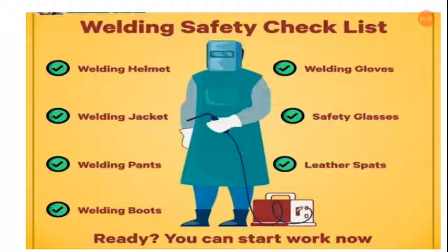Now you have to keep your clothes free of grease and oil. These substances may ignite and burn uncontrollably in the presence of oxygen. Avoid rolling up sleeves and pant cuffs because sparks or hot metal could get stuck in the folds. Wear trousers that overlap work boots, not tucked in, to keep particles from falling into the boots. Leather high-top boots with steel toes are recommended, especially when doing heavy work.